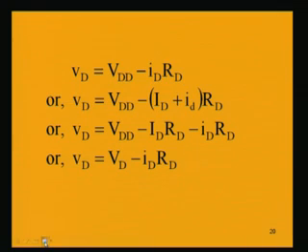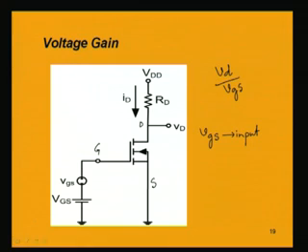So, now let us find out the voltage at this drain end. When we write the voltage equation, we will write the instantaneous voltage equation, that is small v capital D, because apart from the AC signal, we also have the DC voltages, which are required for biasing the Mosfet properly, because we know that it is an N channel enhancement type Mosfet device.